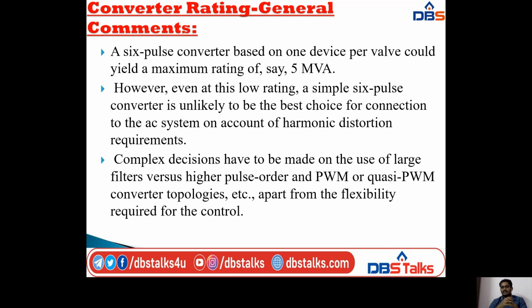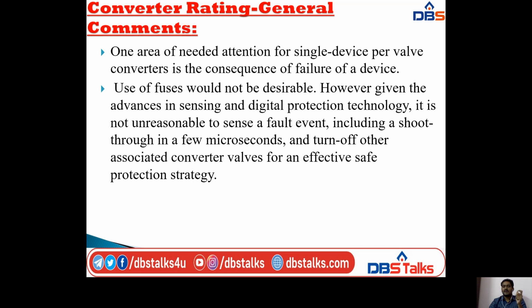Why? Because you may use large filters, higher pulse order, and pulse width modulation or quasi pulse width modulation topologies, apart from the flexibility required for the control. Next, one area of needed attention for single device per valve converters is the consequence of failure of a device.